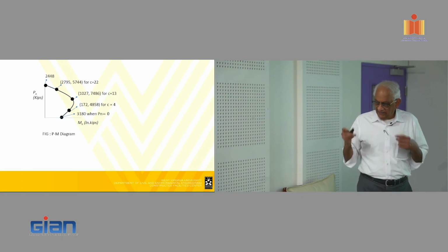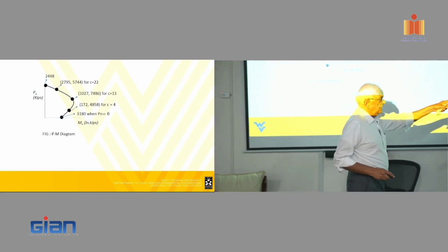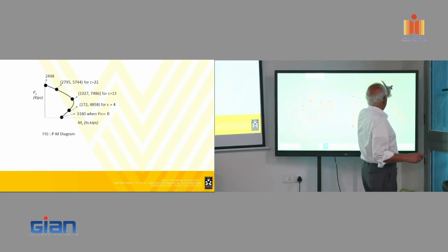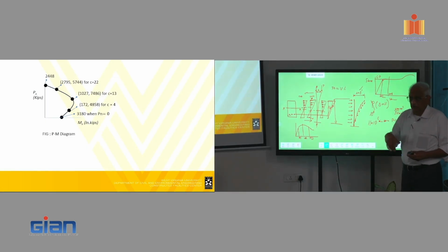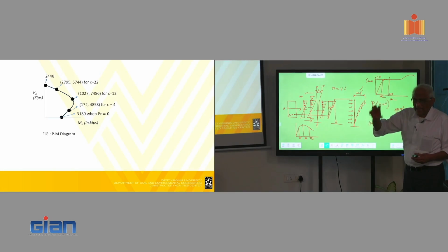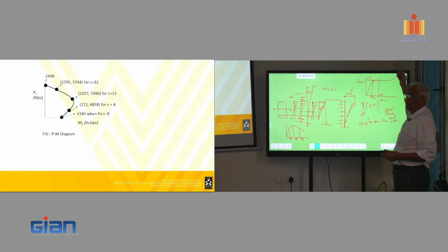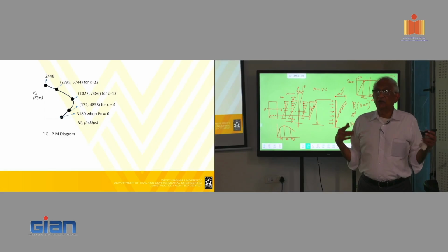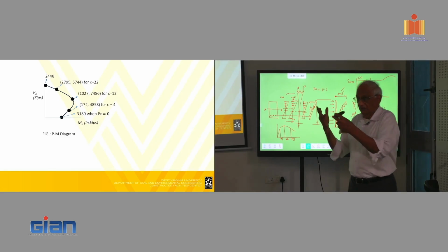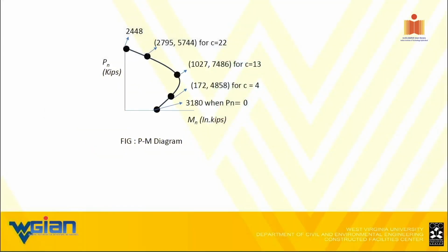I would have said yes, yes, yes, if my... see here for steel, I can never ever exceed the 60 ksi. Yes, sir. And then I could have said what you said, because that's the balanced case, that is the maximum case. But with FRP, even though I'm using 60 or 65 ksi, in reality I'm going much higher, almost, not quite, at least 50% higher, if not 100% higher. Therefore, I cannot say what you are wanting me to say. No, this is a lower bound case. Remember, we are in a design business, not in an analysis business.